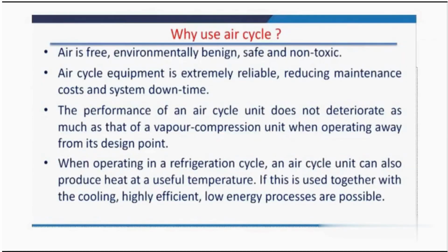Now, we will see why the air cycle refrigeration system is used for aircraft refrigeration. The causes are listed here. The most important cause is that air is going to be utilized as a refrigerant, which is available free of cost. It is environmentally benign, safe and non-toxic.